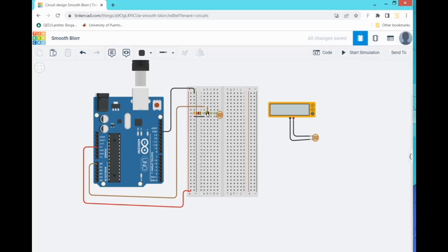Now this connection here is for getting the signal between the photoresistor and the resistor R1 into the analog pin, in this case A0. Since this voltage divider requires 5 volts, I'm getting the 5 volts right from the Arduino, as shown here, into this line through resistor R1. We also require ground, which is installed here for the photoresistor. So we got pretty much everything set.